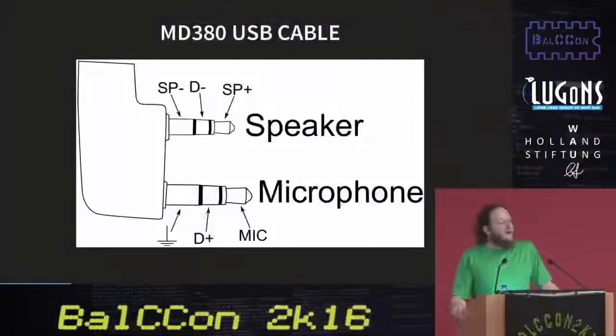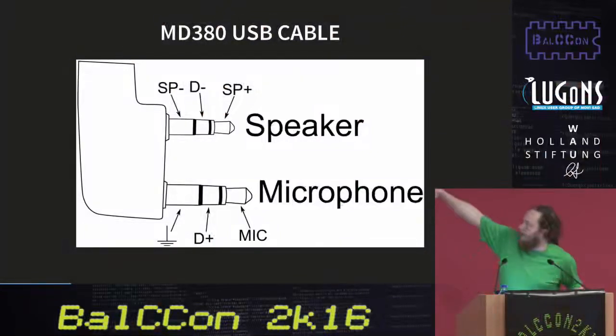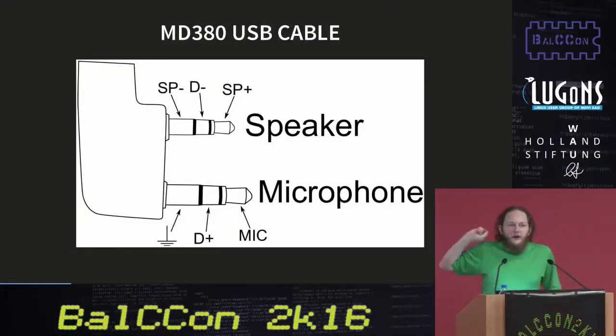The radio supports cryptography, but not very good cryptography. Of particular interest is that the audio cable, the pinouts for which I show here, also contains USB. And it's not a USB to serial chip like many other amateur radios. It's actual USB implemented on the STM32. You can reprogram this chip to do mass storage, or pretend to be a printer or a hard disk or whatever else you like. You could boot from it if you cared to.